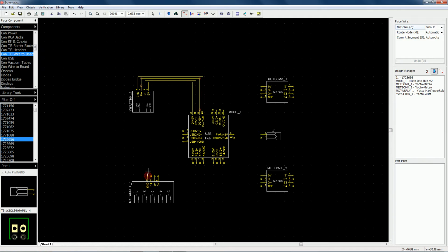We've connected the first device, now we connect the second one. As you see, sometimes the wires don't come in the right order, so you may have to get some crossing. It's not a problem. At this point, it's just a schema, so wires can cross in a schema without making a shortcut. Again, sometimes you need to edit a little bit the wire to make it look good.